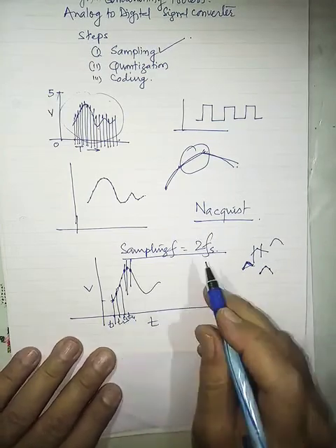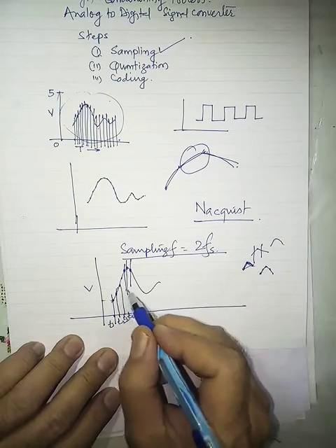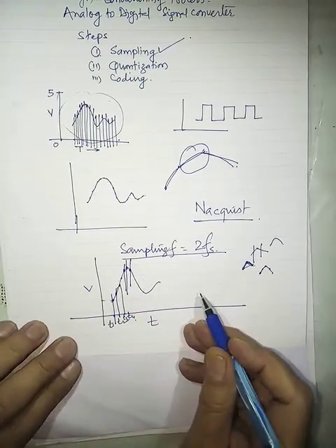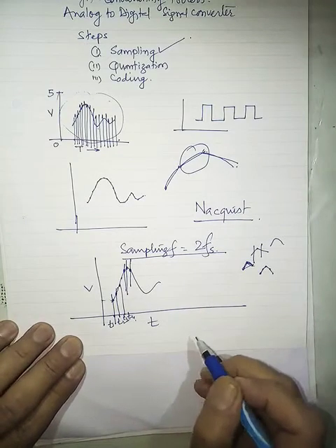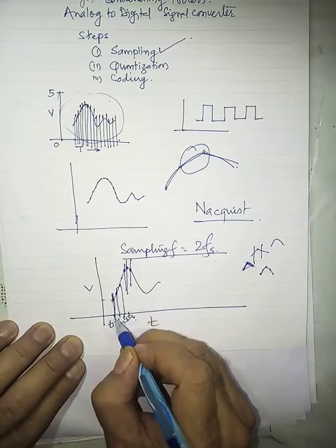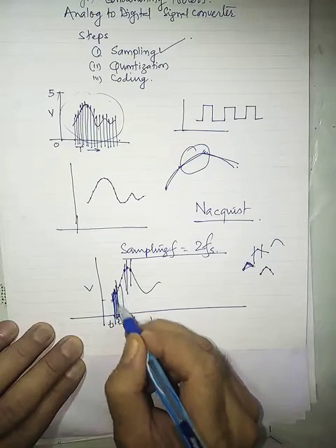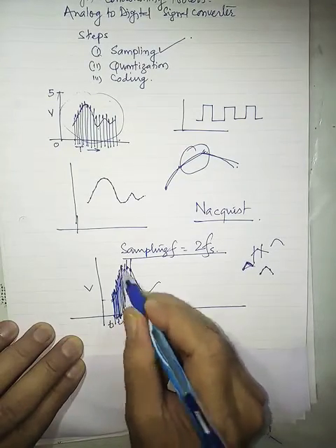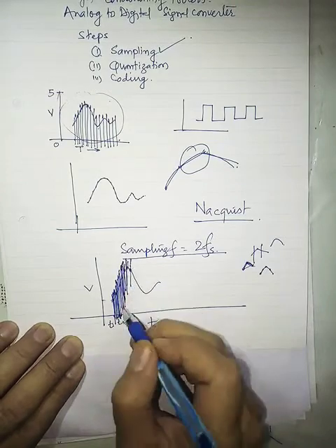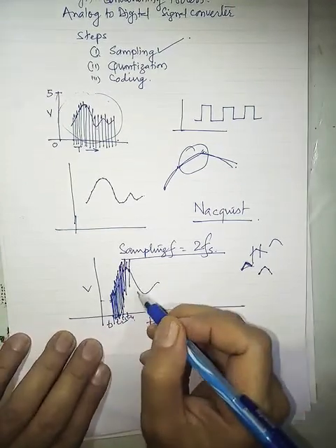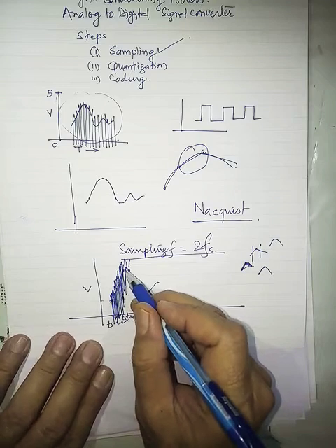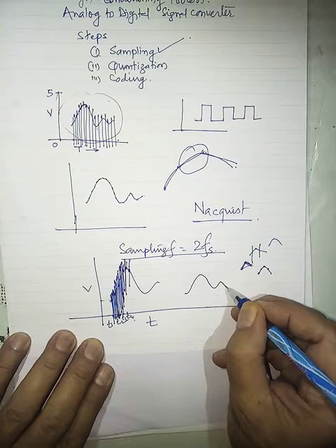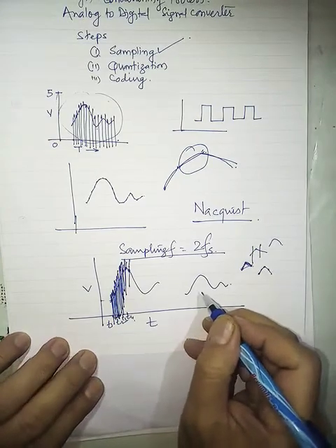You increase the sampling frequency so that no detail is left. That means if my sampling frequency is very high, I take samples at such a small interval of time that no detail is left. If I go this way, then again if I redraw the graph from those digital values, I can have a better result with a higher clock pulse.